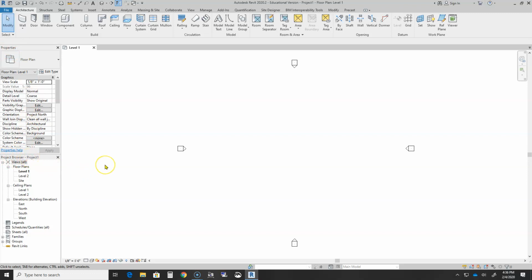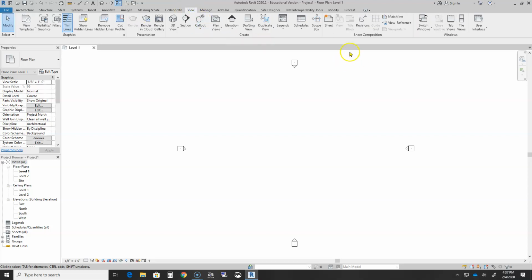Those must stay on all the time. Do not close those just to get a little bit extra space on your screen. Okay, they have to stay open. You will use them continually. A lot of the changes that you'll make in there, a lot of your checks and balances and everything else will be in one of these two panels. If you ever lose these panels, accidentally close one, please don't close one. It's real easy to get them back, however. To get them back, you just click on the View tab here, and then go down to the end where it says User Interface.